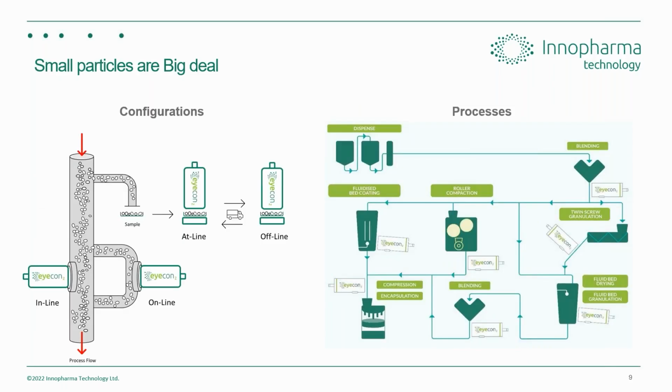Small particles are a big deal in the pharmaceutical industry. Multi-millions of dollars a year are spent on research and development, on quality control, on modifying the size and shape of particles, because it affects everything in the manufacturing process, upstream and downstream. What I mean by that is powders require certain sizes and shapes to flow well from process to process